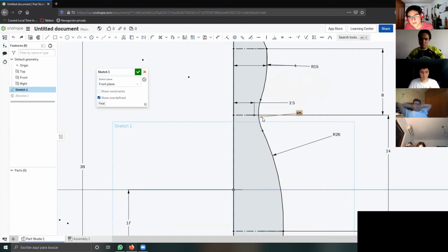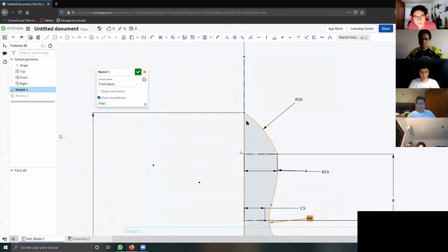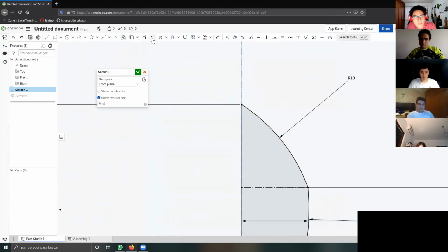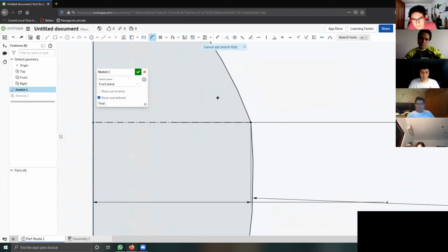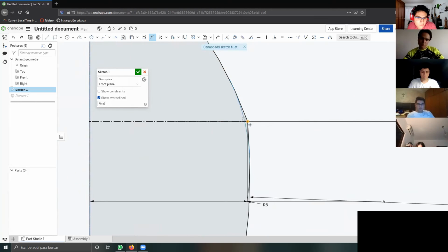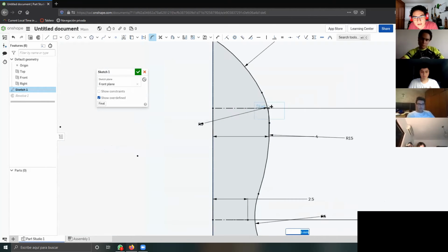Well, I don't know, but I'm gonna do it right up here. I'm gonna use the fillet tool in a corner. And what you do with this is make more round a corner, like here. So now I have a sketch, for example, here, and I click again in a blank space.